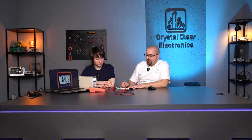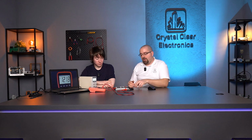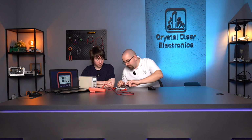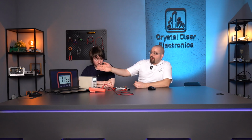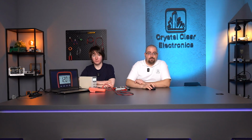Now, I'll put the 1 kilo ohm resistor back again. Perhaps something else could be tried. For example, I could connect two LEDs in series instead of one. I can do this by having two LEDs in series here and just switching the current meter. Now you can see that both LEDs are on and the current is still at this 12 milliampere value.